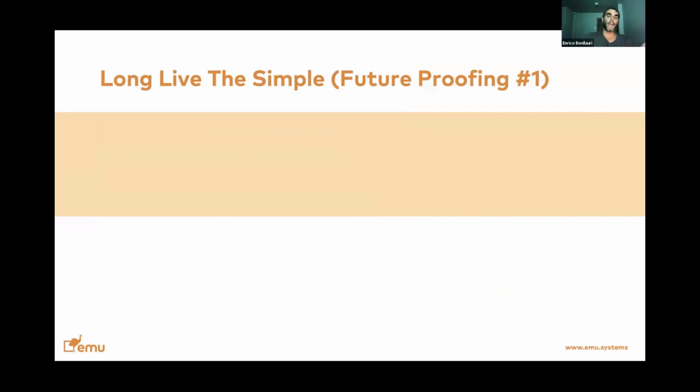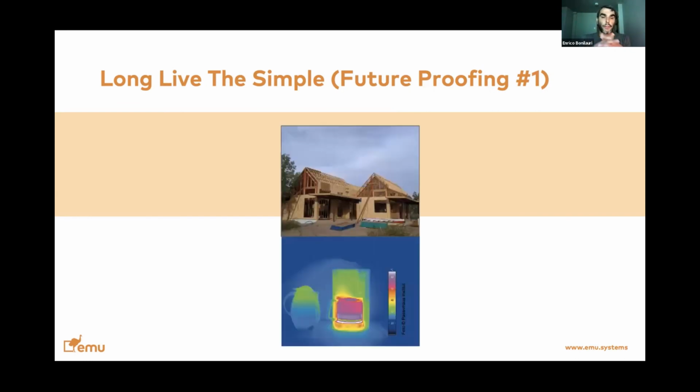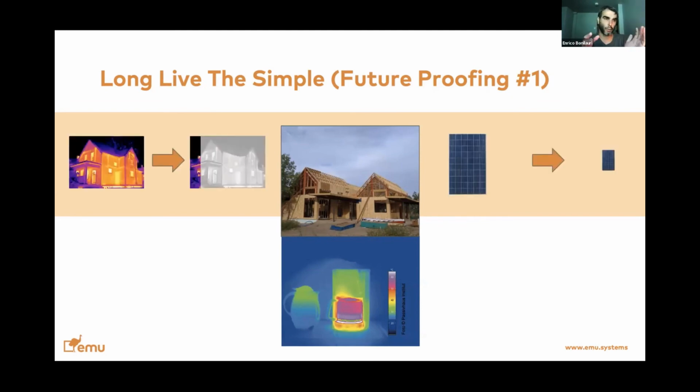If you put all of that together, you come up with a building that is actually very simple. You have a thermos, and from a technology point of view, a thermos is a box that is very highly insulated but has very few moving parts. Even an HRV or ERV, the ventilator, the moving part in that is just 2 fans. The heat recovery core is static, it does not move. So it's a very simple system. And if you reduce your heat losses, the energy you need, shown on the left-hand side, by 75 to 95%, then your mechanicals become extremely small.